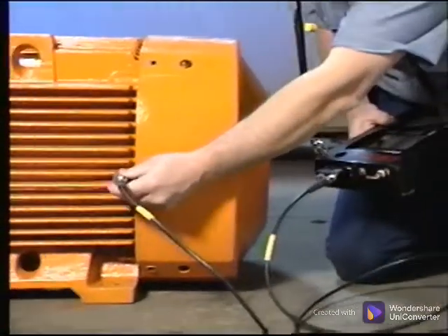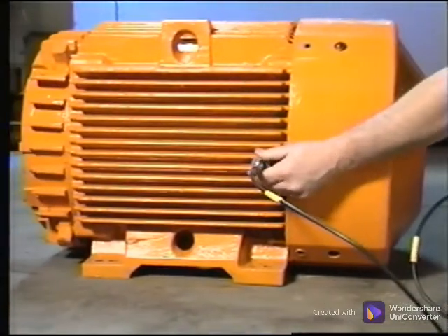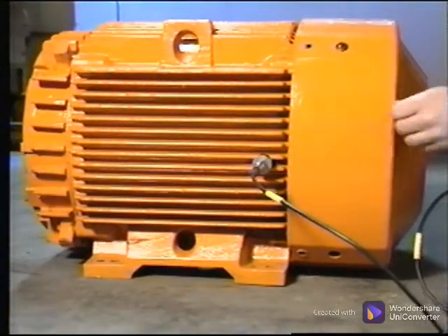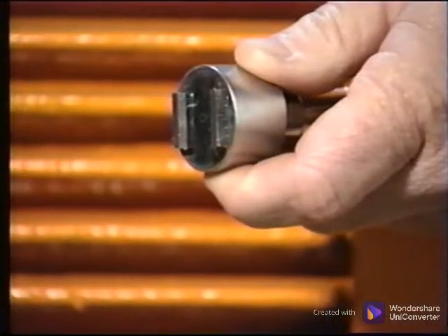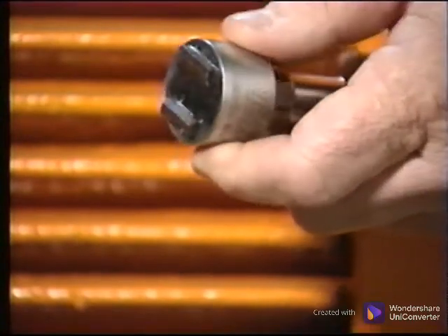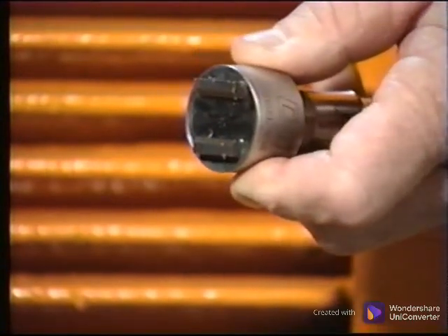The alternative is to collect data through this area of the motor. With these cooling fins spaced closely together, it becomes necessary to place the magnet mount on the fins. It could be placed across the fins or in line with them if the magnet's two poles will line up.